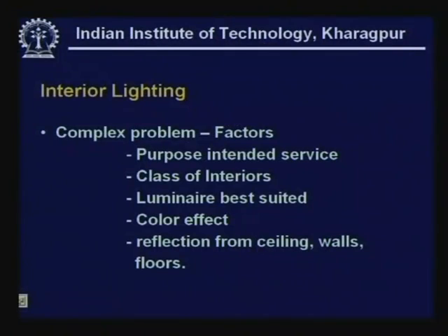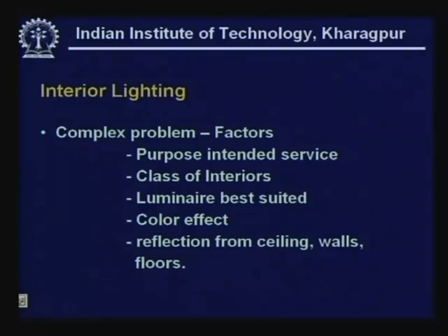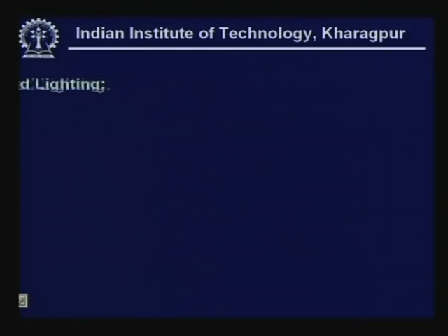And in fact, one other issue which becomes very crucial and one of the common mistakes in a lighting design is glare, and that can arise from the reflections, if proper reflection factors are not chosen and the colors of the furnishings vis-a-vis the walls are not matched. These are some of the issues one needs to keep in mind.